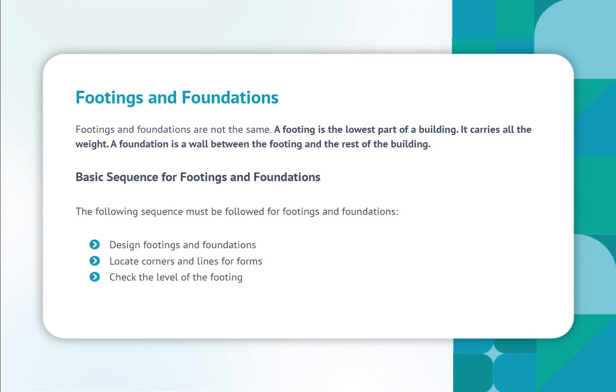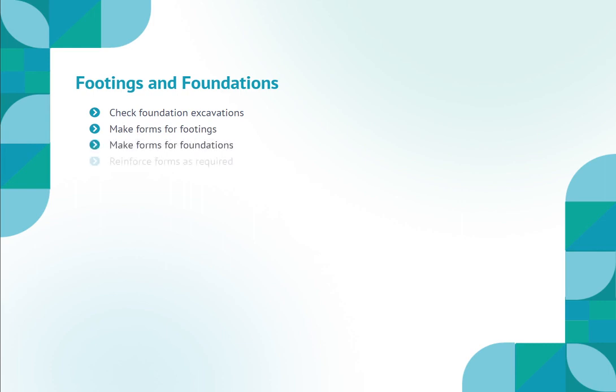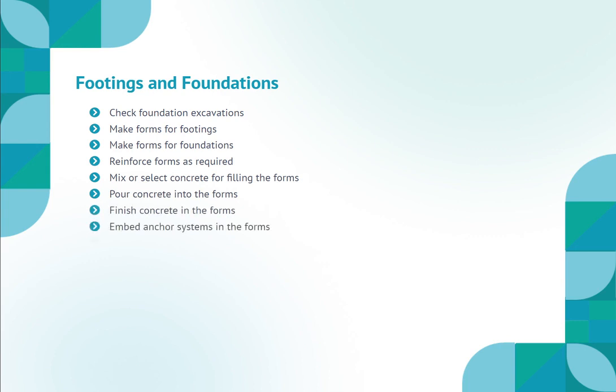Basic sequence for footings and foundations. The following sequence must be followed for footings and foundations. Design footings and foundations. Locate corners and lines for forms. Check the level of the footing. Check foundation excavations. Make forms for footings. Make forms for foundations. Reinforce forms as required.